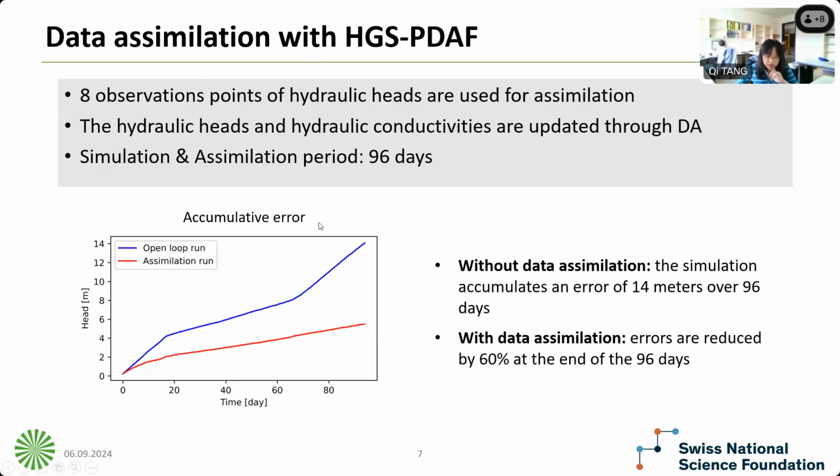The data assimilation method we use in this case is a standard ensemble Kalman filter. So the ensemble size we use is 100, and the simulation period is 96 days. In this case, we update both the hydraulic heads and the hydraulic conductivities by EnKF.